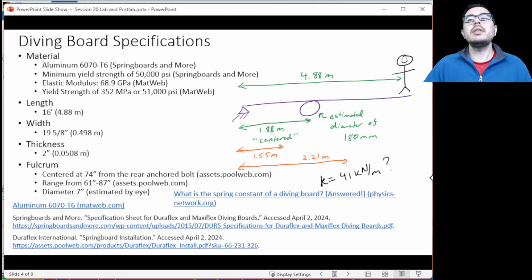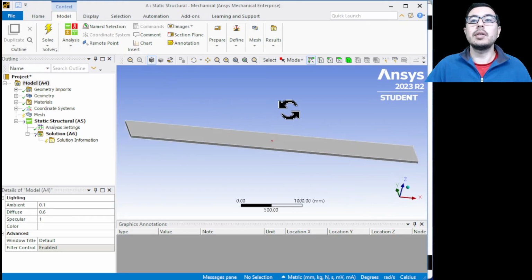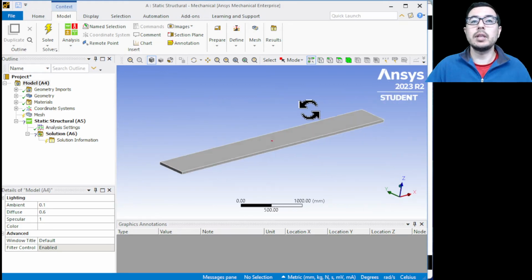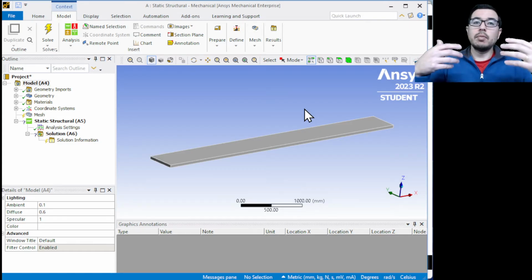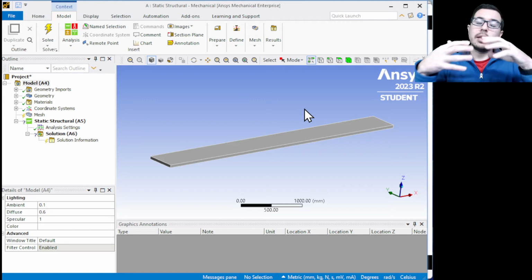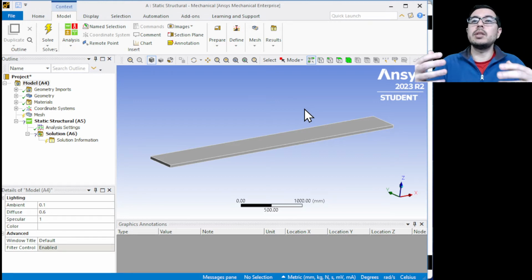We will need to be a little bit careful with the stresses that we calculate, because there can be concentrations in close proximity to these supports. So I'll show you how to handle that, and essentially we're going to ignore some of those extremely high stresses because they're concentrations. As the real material with bolts and washers and nuts, they're able to relieve some of these stress concentrations. It's not just at a line or a point.